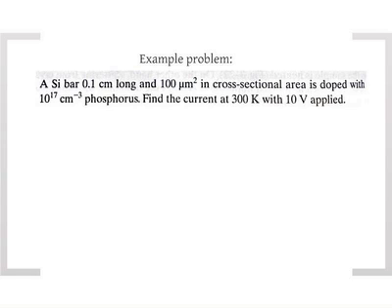Wait, how did you find conductivity? I was writing stuff down. Here, this is from last class. Conductivity is given by mobility times the charge times the number of electrons. Of course, if you want to do this rigorously, you need to also consider holes as well. But it is such highly doped material, you can ignore the holes. It's mostly electrons. And we are talking about drift current right now. This was from last class, so go back and review if you don't remember.